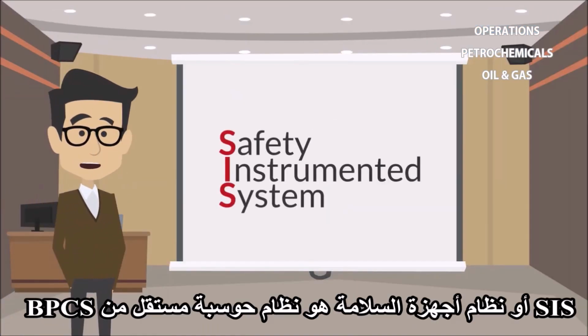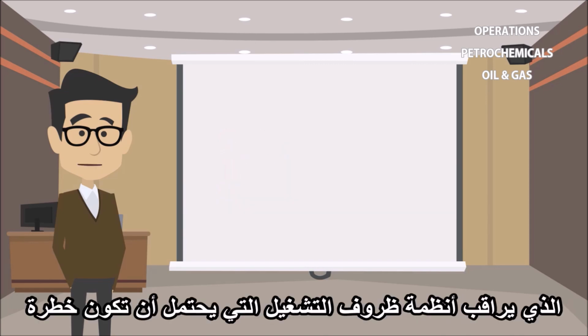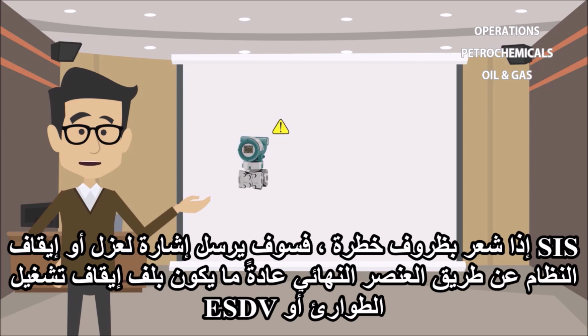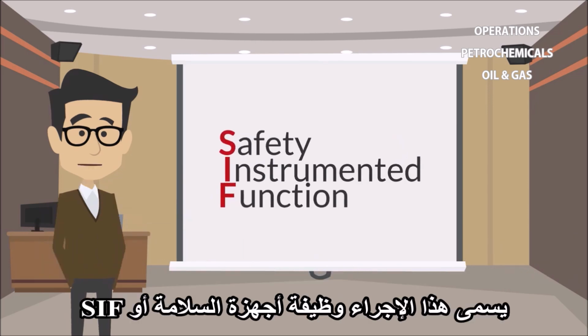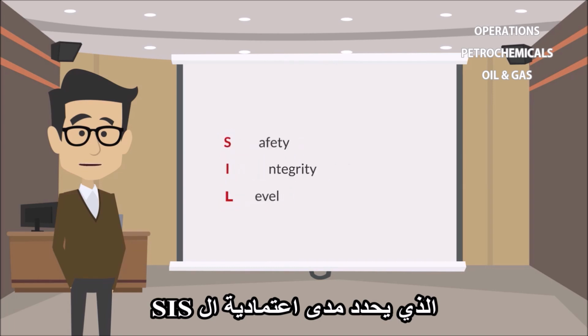A safety instrumented system, or SIS, is an independent computing system from the BPCS, which monitors the system for potentially hazardous operating conditions. If the SIS senses a hazardous condition, it will send a signal to a final element, typically an actuated emergency shutdown valve, or ESDV, to isolate or shut down the system. This action is called a safety instrumented function, or SIF, which may have an associated safety integrity level, or SIL rating, which quantifies how reliable the SIF is.